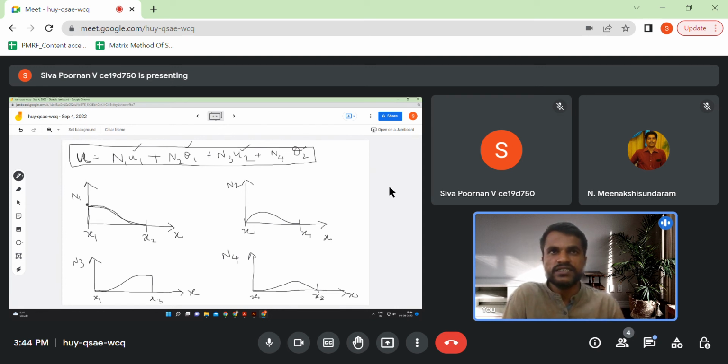Here we are only interested in giving a unit displacement at one point and making all other degrees of freedom 0, which gives us a deformed shape. That deformed shape is the shape function. Okay, that's the difference between what we did while finding the stiffness matrix and what we are doing here. Although there also, while finding all the 4 columns, we did a very similar exercise of making one degree of freedom 1 and everything else 0. There we were only finding statics, the end forces generated due to that displacement. Here we are finding the deformation caused by a unit displacement.